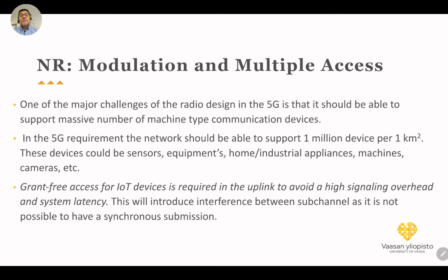And also there is another problem. Even if we provide a new RF with a very large number of subbands, enough for the required number for IoT, we still have one critical problem. Usually in normal 4G or OFDM communication, there should be synchronization in order to keep the orthogonality between devices. So we should, for example, allocate a certain number of subbands for each terminal in the uplink, and then we have some synchronization in when they send their messages, so that we can keep the orthogonality between them. If we miss this, then we have, for example, inter-carrier interference between the subcarriers.